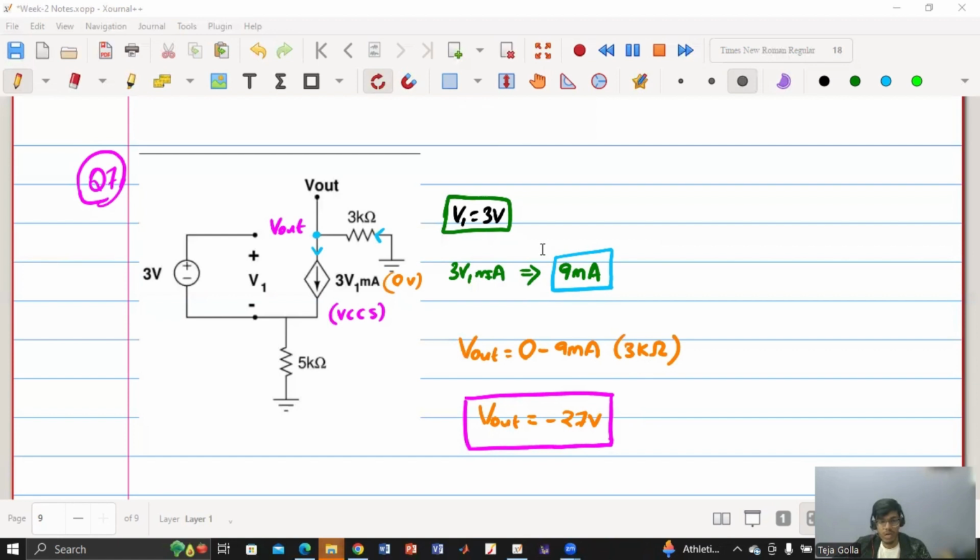Okay, yeah. Sri Vishnu Vardhini, today's session is almost over, and I would request you to solve with this approach. First, see what they are asking in the question, what current, what voltage. Then try to assume the direction of currents if they have not been given, and then calculate the currents and voltages one by one by applying KCL and KVL.